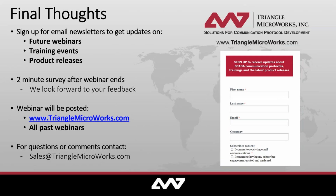You could have a similar application running on your local HMI of the station, or you could even imagine to report those information forward to the SCADA. Not sure if the SCADA really needs everything, but yes, I think it's a good idea to put those information in a report and have somewhere a visualization of how your GOOSE messages are subscribed currently in the system.